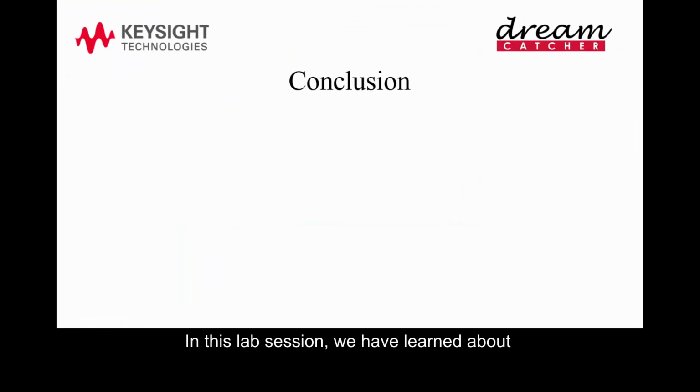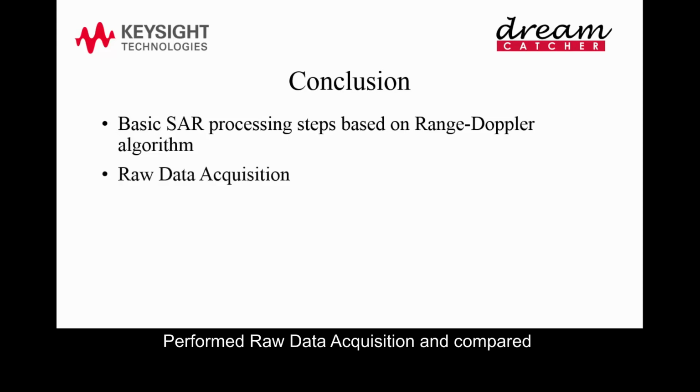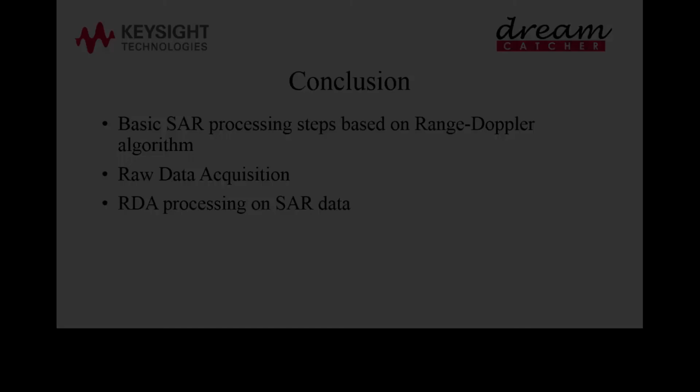In this lab session, we have learned about basic SAR processing steps, based on range Doppler algorithm. Performed raw data acquisition, and compared the real aperture radar and SAR images. Performed RDA processing on SAR data, to generate a 2D SAR image.